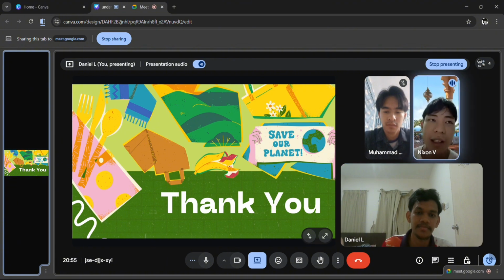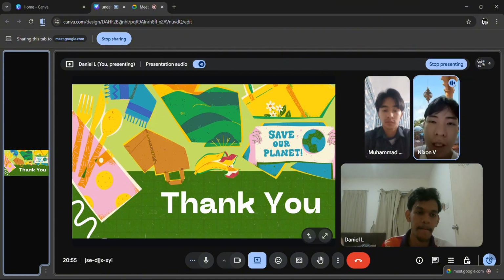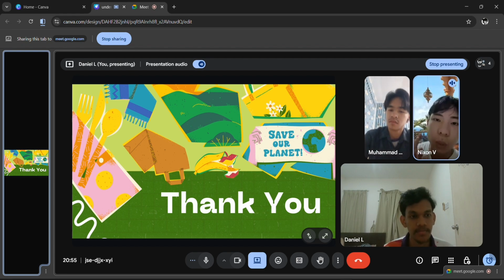Okay, thank you guys. And now I'm going to simplify everything again, in simpler and shorter terms. Basically, what you need to understand for a solar system is the main components. What components are involved in a solar system? The basic things are just the solar PV panels, which go to the charge controller. The charge controller charges the battery, and then we have the inverter. The inverter changes the DC output supplied by the battery to AC output, and then from the inverter it can go to the load.